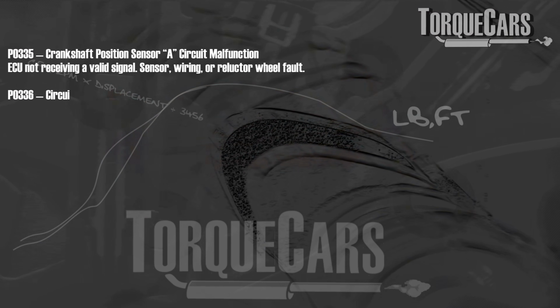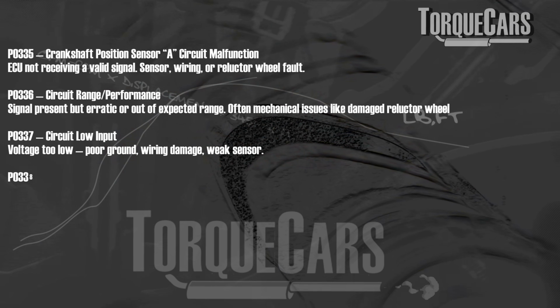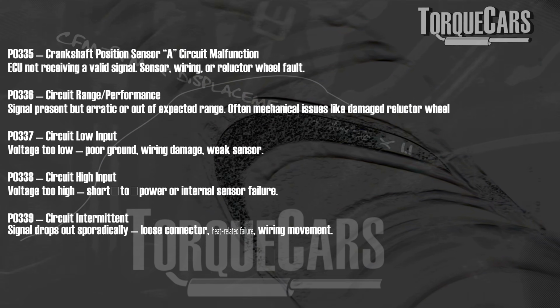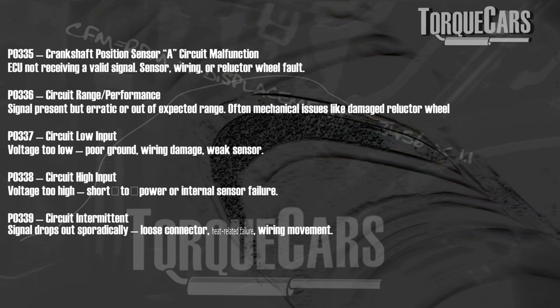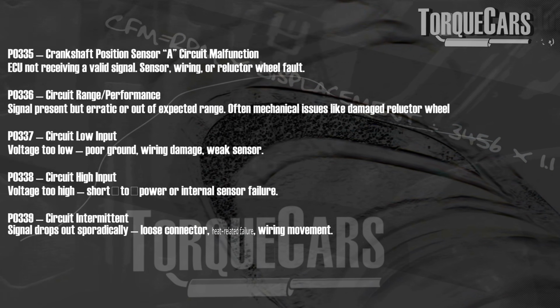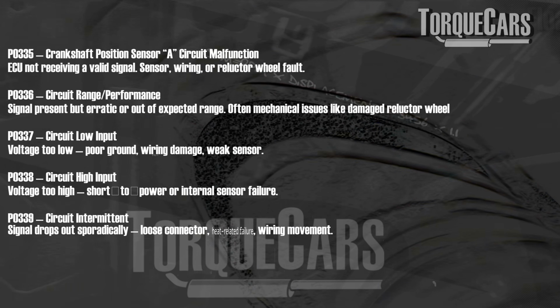Error codes to look out for are P0335, 336, 337 and 338. Fault with the circuit, fault with the range, signal low and signal high. If you're getting the P0335 and you're not starting, it's almost certainly going to be down to the crankshaft position sensor.